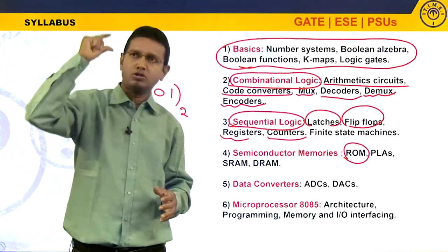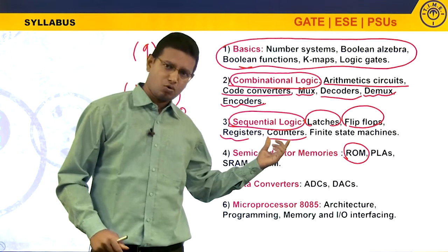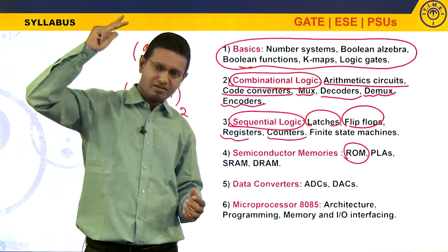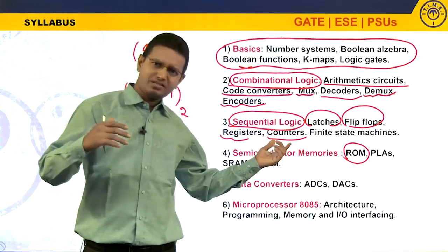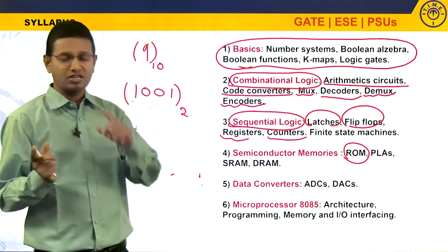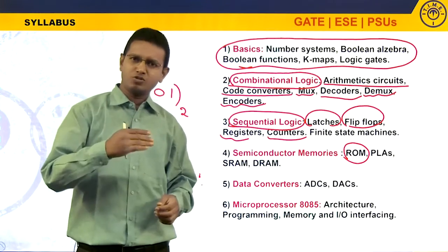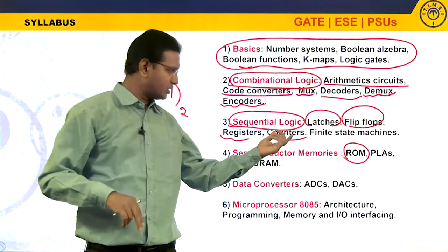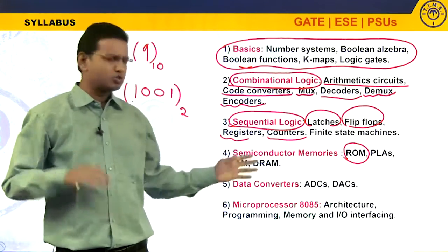Exactly at the door, on the top of the door, they will fix a device called an electronic counter. Whenever a person goes in, the electronic counter will get triggered by a mechanism of sensing, and a clock pulse will be generated. That clock pulse will be recorded by this counter. When the second person goes in, again the triggering will happen, a clock pulse will be generated, the states of the flip-flops will change and it will be recorded, and so on.